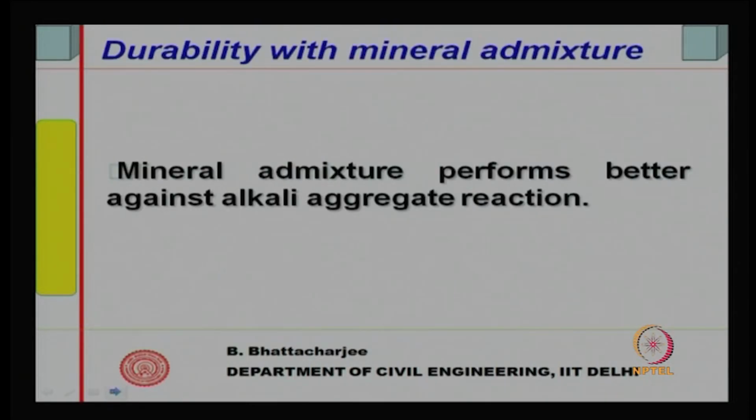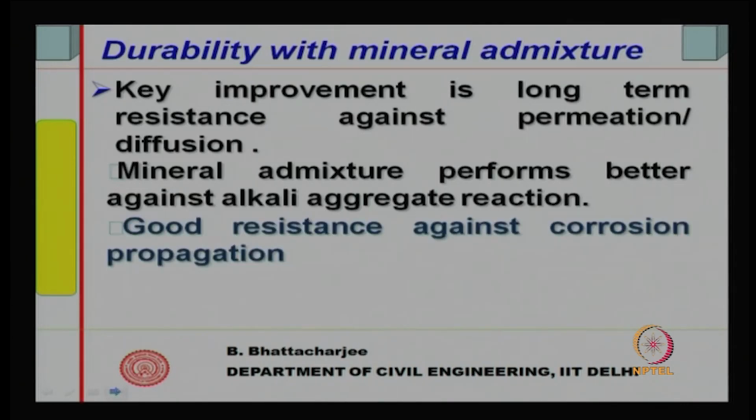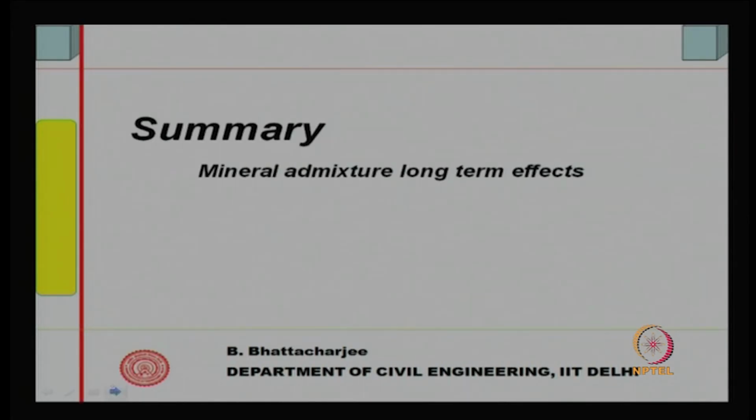So, mineral admixtures perform better against alkali aggregate reaction, this we know, because permeability and diffusion reduce, and the better pore structure reduces moisture ingress, and therefore, mineral admixture performs better against alkali aggregate reaction, with good resistance against corrosion propagation. Against magnesium sulphate it is still uncertain at the moment. There are some reports that they are not very good against magnesium sulphate, but against other sulphate attack they are again better. So, mineral admixture generally improves durability properties of concrete as well. This will be again further discussed when we talk of durability.